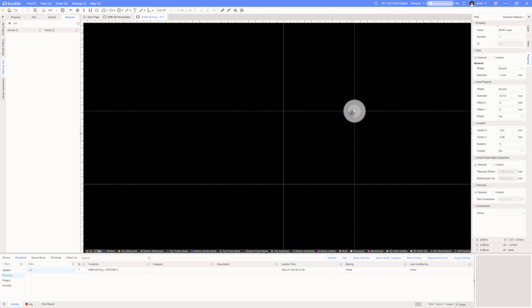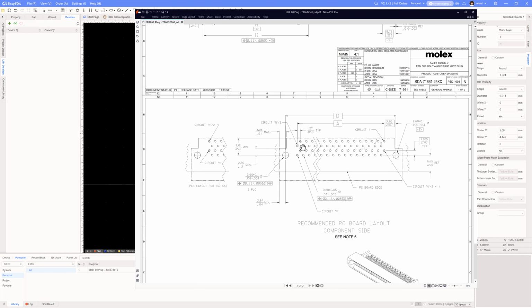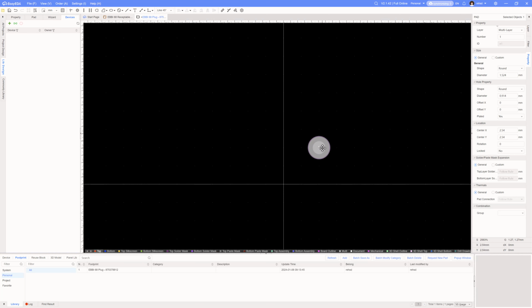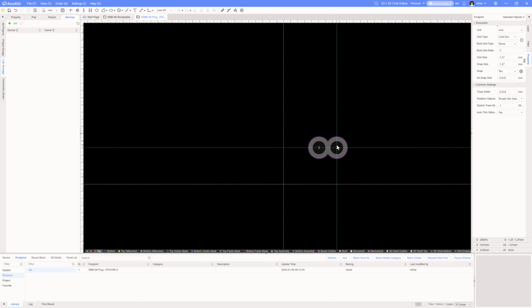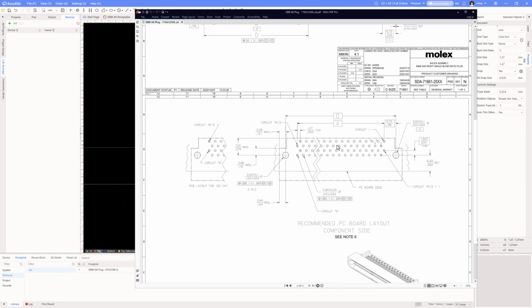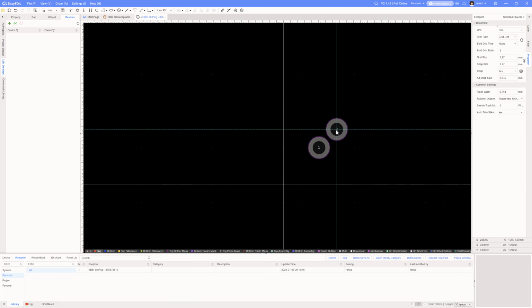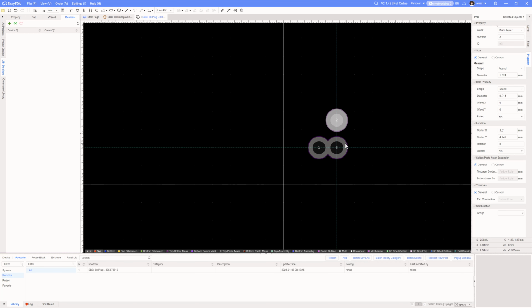Okay, so when I drag, it'll drag by default 1.27, but if I hold down the Alt, it'll drag half of that, is what I'm doing there. Coming back over here, I want to go one full grid spot down and another half. That would give me my 1.95. I got this, and I'm going to add some more. The next one, I want to be one grid over and 1.5 up. So there's my Alt drag, which gives me my 1.5.